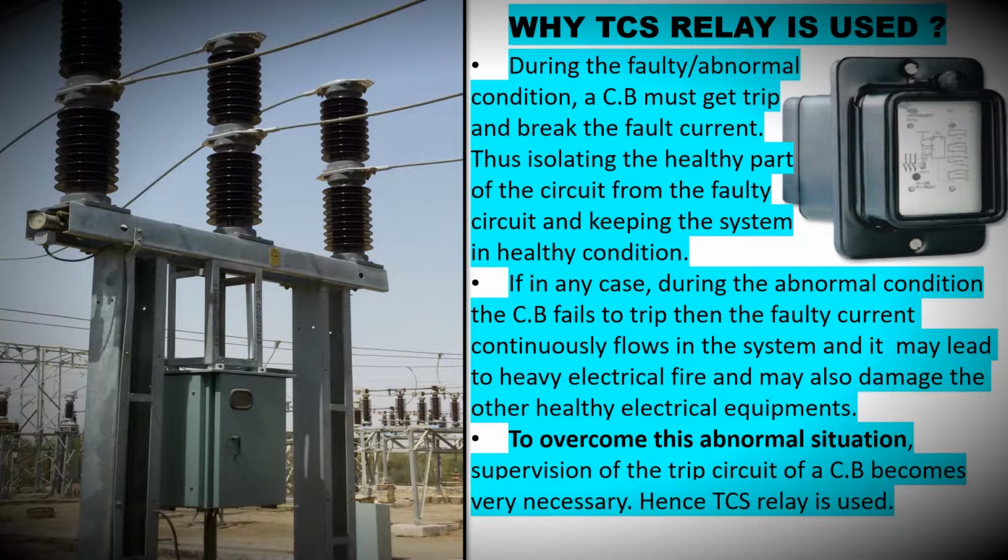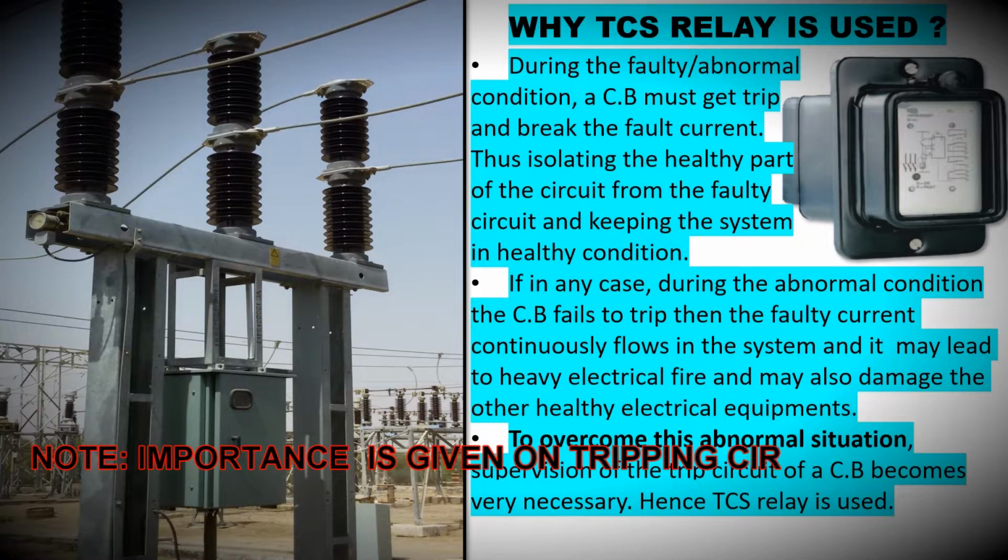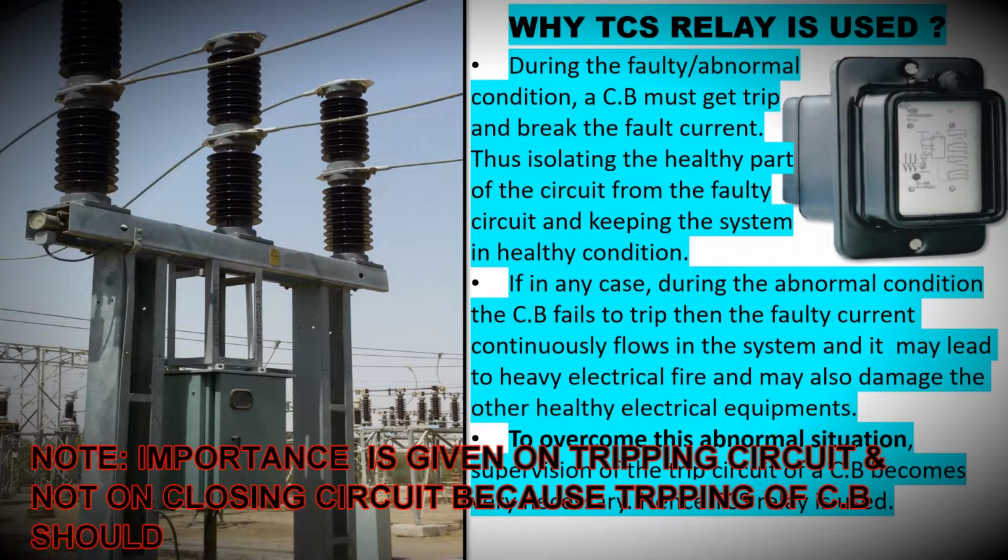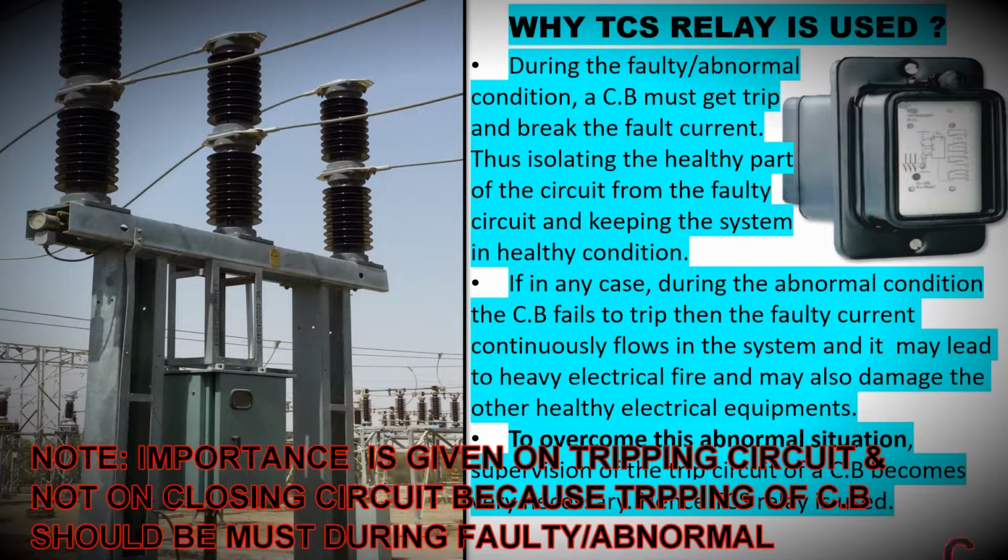Also, one must note that here the importance is given to the tripping circuit of a circuit breaker and not to the closing part of the circuit, because tripping is very necessary during the faulty condition. Hence, supervision relays are only used in supervising the tripping circuit of a circuit breaker.